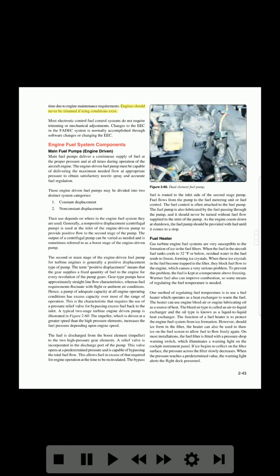Engines should never be trimmed if icing conditions exist. Most electronic fuel control systems do not require trimming or mechanical adjustments. Changes to the EEC in the FADEC system are normally accomplished through software changes, or changing the EEC.